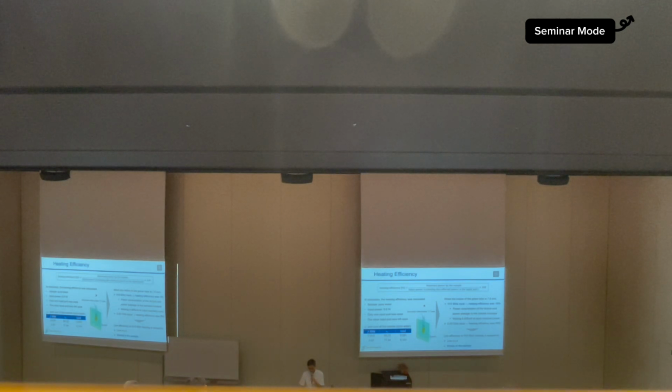When the radius of the glass test tube here is 7.5 millimeters, if we input 915 MHz, the heating efficiency was only 19%. And if the frequency was 2.45 GHz, the heating efficiency was 89%.